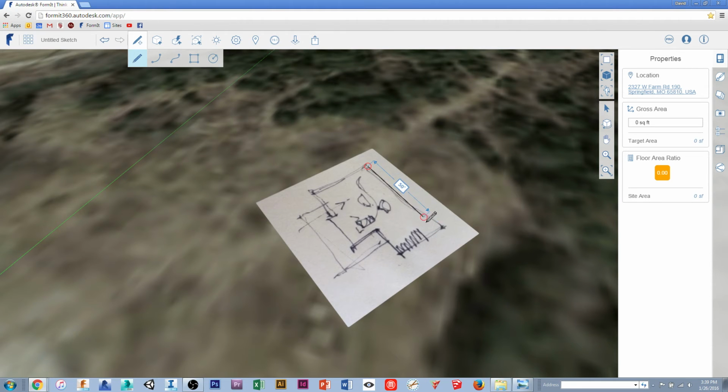Well, that seems a little bit off. Oh, that's because out to out on the image is going to be 80 feet. I want this back wall to be about 80 feet. So we do need to scale that up a little bit. That'll be pretty simple. Let's go ahead and select that. So that line right now is 60 feet. Let's draw that line one more time. Let's draw that line at 80 feet. And then we're going to scale this image up to match.